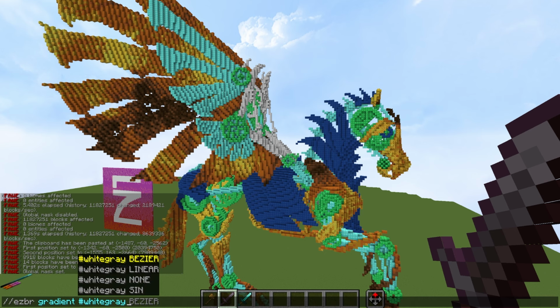Even though this autocomplete goes into the interpolation next, you can actually enter a brush radius next. I don't know if that's something that needs to be fixed or not, but the next thing to enter is a brush radius. I think if you don't define the radius, it's set to 8 by default. So even if I just set the interpolation, it's going to use a brush radius of 8, which is fine. I'm just going to set my radius to something a little bit bigger, like 15. And then you have your different interpolation types, and I can explain what those are to you.